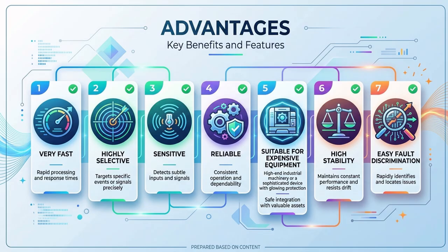Why is differential protection so widely used? Because it's very fast, highly selective, sensitive, and reliable. It protects expensive equipment, offers excellent stability, and accurately distinguishes internal faults from external ones. That's why it's one of the most trusted protection schemes in power systems.